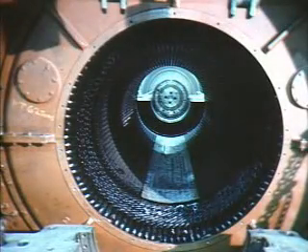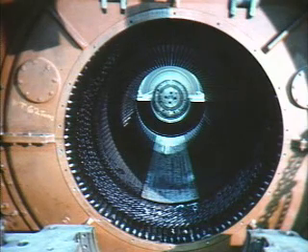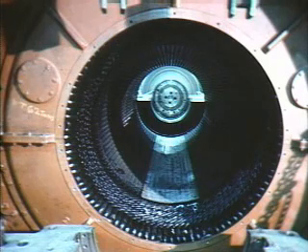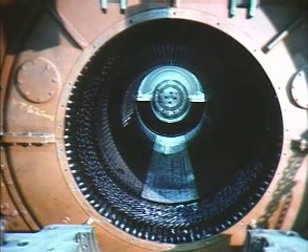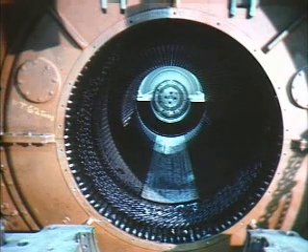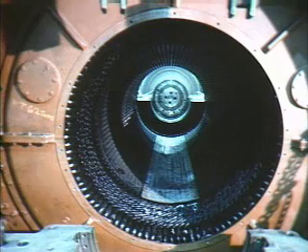If the cooling system doesn't function properly to remove heat, the excess heat can cause the insulating material inside the generator to break down, which can lead to electrical faults. When the insulating material begins to decompose, small particles are produced that are picked up by the hydrogen. These small particles are commonly called particulates.